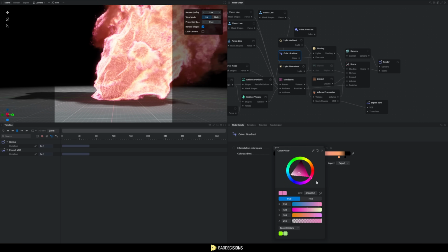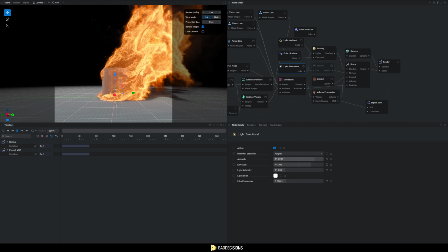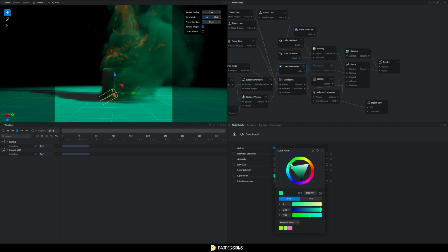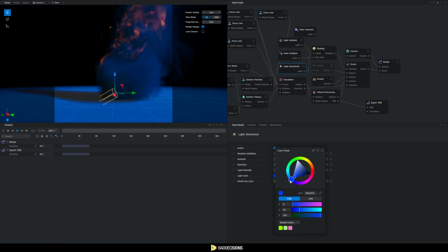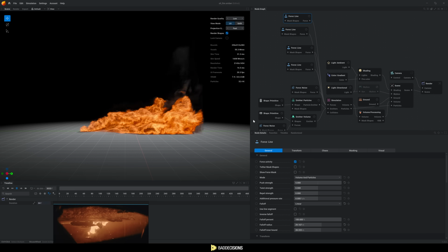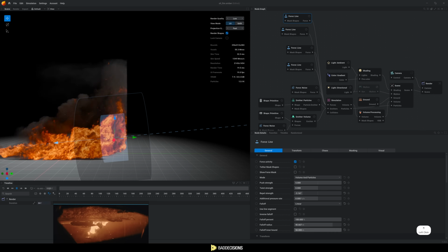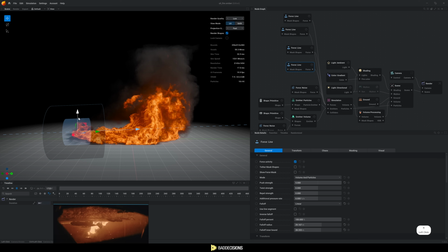This also can be changed inside Unreal Engine, so don't worry too much about it. Finally, we have the lighting settings, but these are only for previewing inside Embergen. They do not impact what we export to Unreal Engine. What really matters is the shape of the fire and the forces we give it, plus the simulation. That's how we control the movement and the dynamics of the flame.